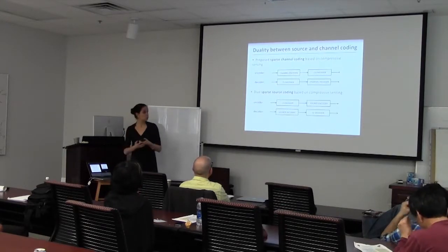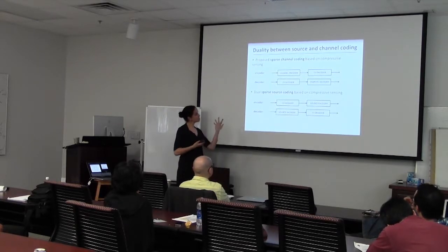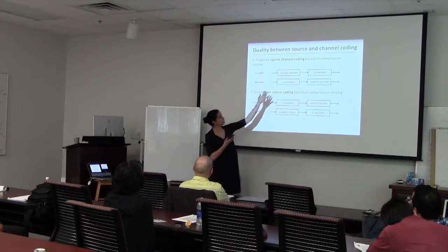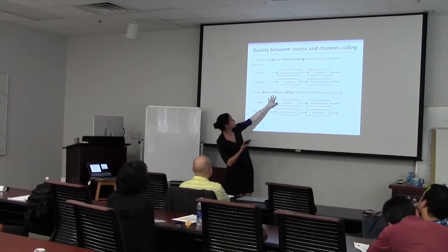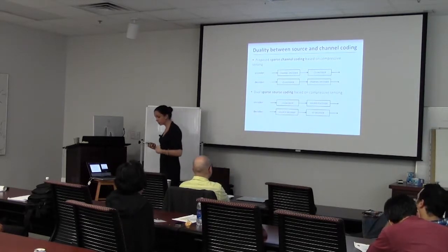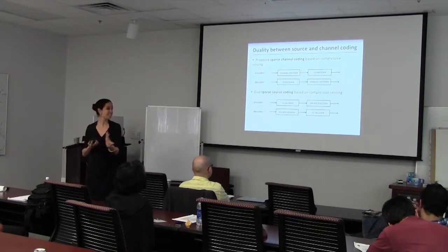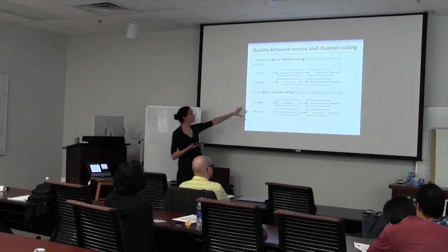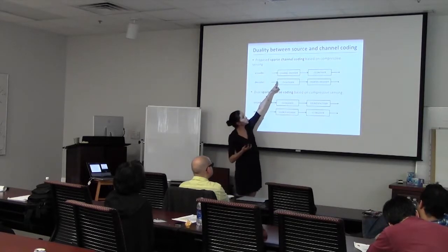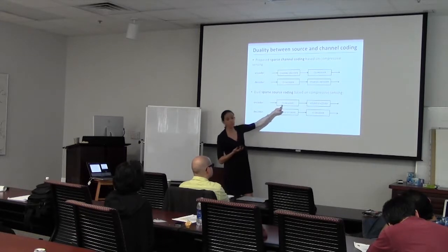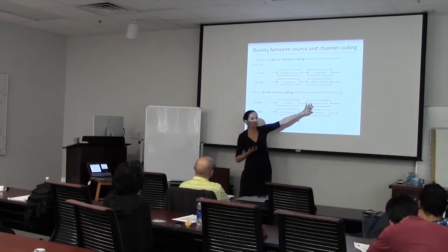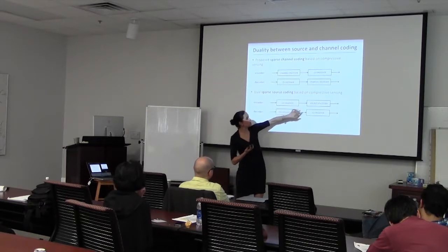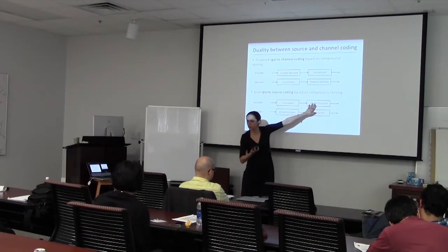So again, I would never do this for source coding, but for channel coding. But maybe whenever I do channel coding, I can think of doing the reverse, the dual, which is just the source coding. So I could think of doing the sparse channel coding, and the reason I started with that was because it's closer to the original compressed sensing problem. Or I can think of doing source coding, and if here I was doing first a channel encoder and then the CS encoder, what's going to happen here is I'm first going to do the CS encoder, make it sparse, right, and then put it through the source coder, right? This is basically, I'm sparsifying it over here, which means it's going to be easier at this level to do things. Does it make sense?